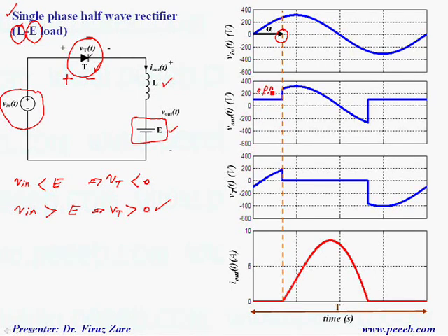And because the current through the battery is 0, the output voltage is basically equal to the battery's voltage. Over this period thyristor is on, and if we look at the zero crossing or any point except this time, we can see that the current through the thyristor or output current is positive.